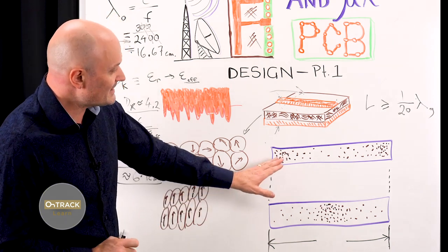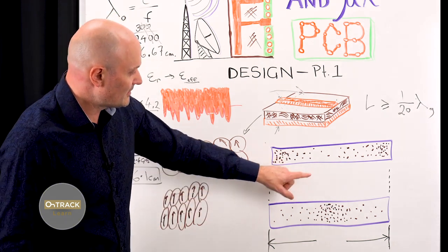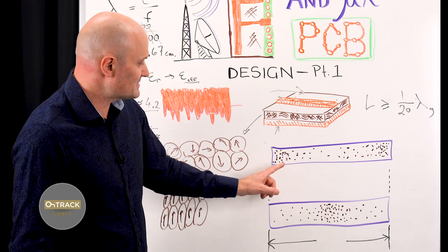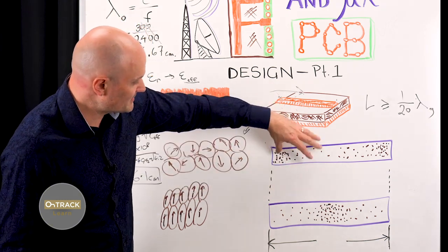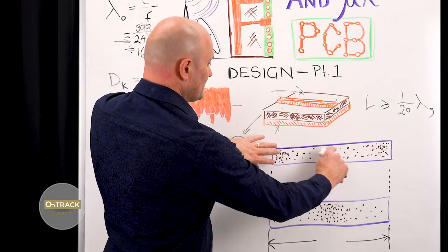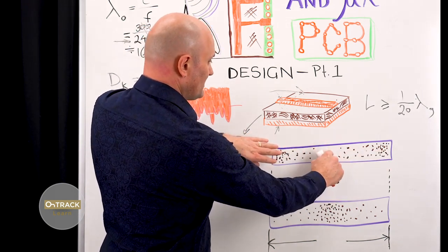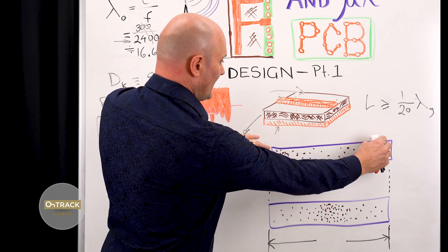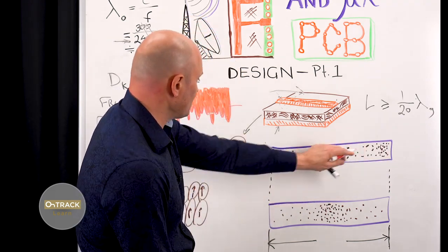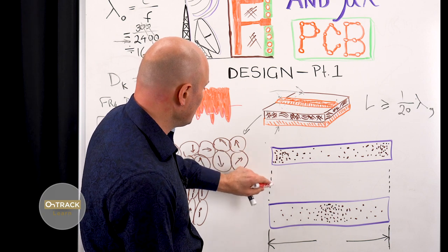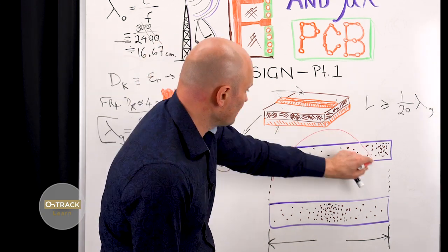So in any conductor, we can place a voltage source and have the electrons at one time instant all go away from the middle. So we have a net positive charge in the middle of the conductor and negative at the extremities. If we could graph the voltage over the distance of this conductor, we'd see this kind of waveform.